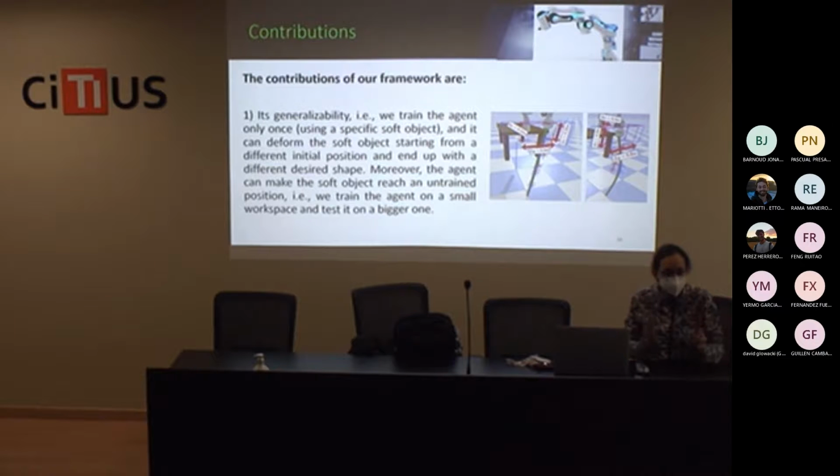Of course, the training is performed for the same specific object; we cannot change the object yet. This is done because I'm mainly using different deformation boxes. As you can see in the figure, the blue box is a box within which the arm can move, so this is the workspace of the robot. Then we have two red boxes. Both are used to make the gripper move within the box, randomly or sequentially, it doesn't really matter. And when the robot moves, the object is deformed differently.